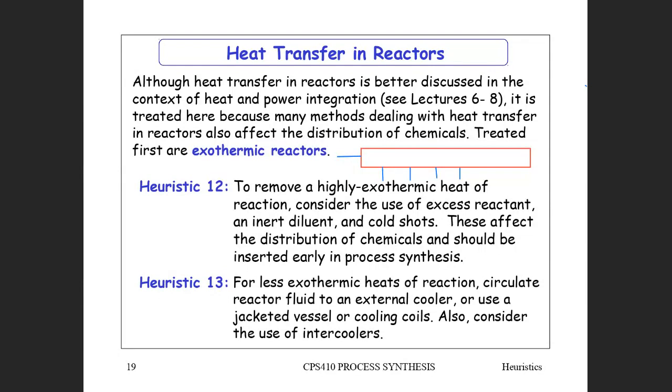And that cools down. So this goes up to, let's say, 300 degrees C due to the heat of the reaction. You put in some more cold reactant at 25 degrees C, and it cools down to 200 degrees C. It rises again to 300, cools down to 200, rises to 300, all along the reactor.